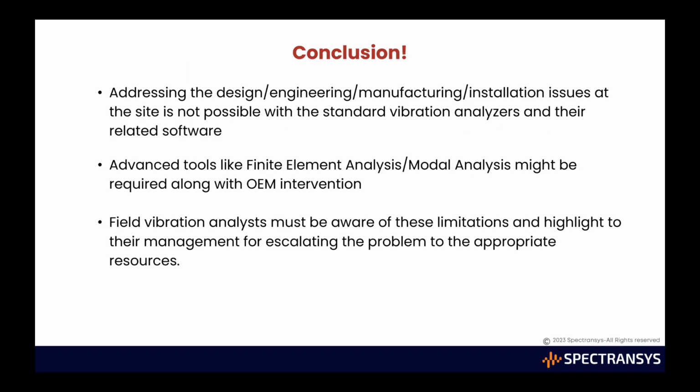So this is the conclusion. Addressing the design, engineering, manufacturing and installation issues at the site is not possible with standard vibration analyzers and their related software. Even a category 4 specialist doesn't have the complete tools to analyze the problem. So advanced tools like finite element analysis, modal analysis, etc., along with OEM intervention, are required to address these problems.